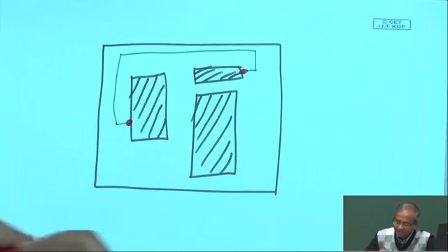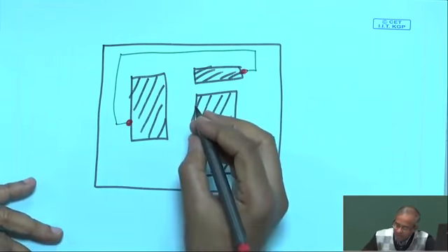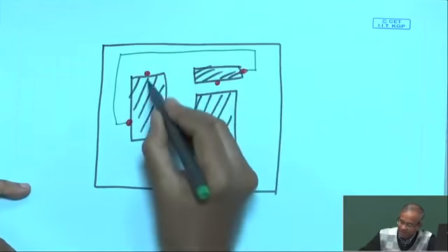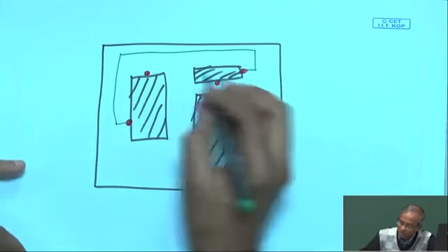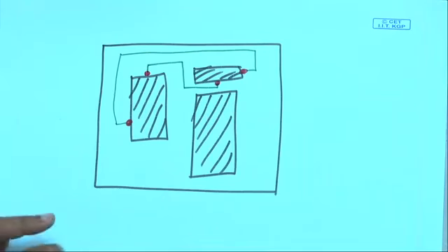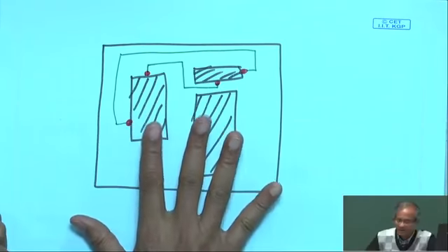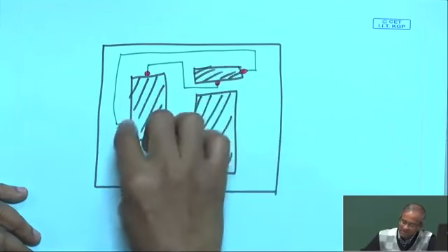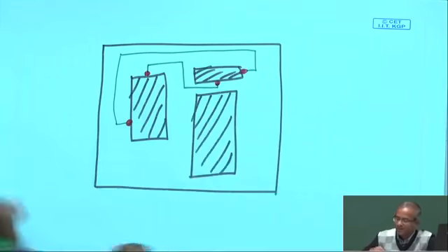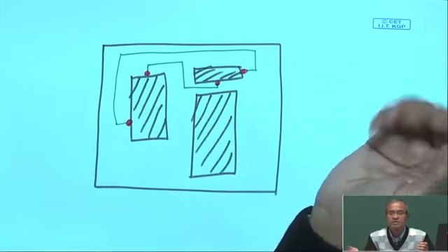Now, say I have another problem next, where I want to connect a pin here with a pin here. Obviously, since we have laid out this line on the same layer, you cannot follow the same route because there will be a cross. So, here possibly you will have to take a route like this. This is the problem of grid routing. There are obstacles, there are pins to be connected. Try to determine a path, typically as short as possible, so that you can complete the interconnection.